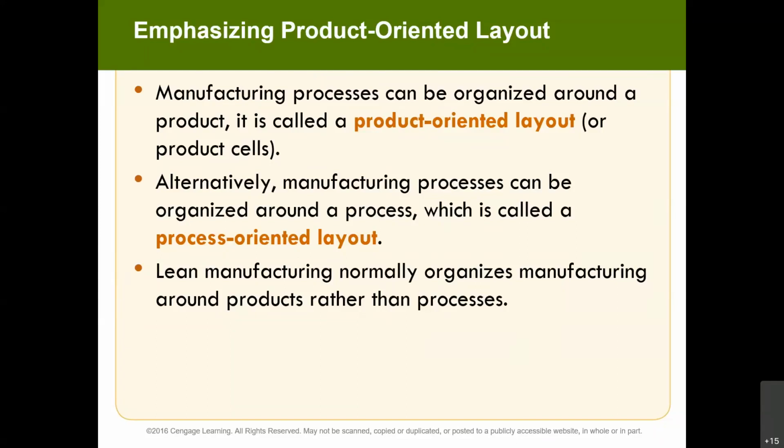And then if I reduce the amount of time it takes to get from the machine to the assembly stage, with that logical layout, I'm improving the overall efficiency and I'm becoming more lean in the manufacturing process. So that's the whole concept behind process-oriented layout. You've got raw materials close to your machine, which is close to your assembly, which is close to your packaging. That logical flow of the materials, that is the process-oriented layout. And so the more logical that flow is, the more lean the manufacturing process becomes, because you're taking less time in that process. So manufacturing can be organized around these processes.